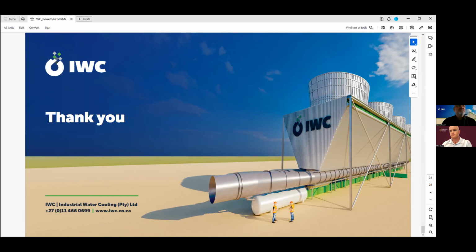Now, how this works, Matthew, thanks for the question, is the steam turbine power output is determined by the pressure difference across the steam turbine. And with this pressure difference, the cooling system determines what the outlet pressure is of the steam turbine, and ultimately how much power you can extract from the steam. If you use a wet cooling system, you can achieve a much lower pressure at the steam turbine outlet than you can achieve with a dry cooled system. As a result, you get more power output in a wet cooled system than a dry cooled system.